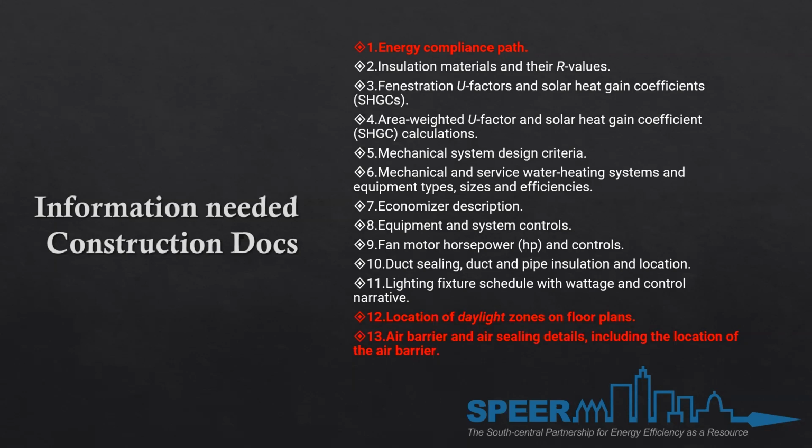Some people look at it and say, well, the 2021 IECC is a model code for us to build off of. And if you use it that way, then you amend it how you see fit for your constituents and your building industry that's in your community. So are credits required? Yes. By the book, all of them are required on any building type. And you have to hit 10 points.